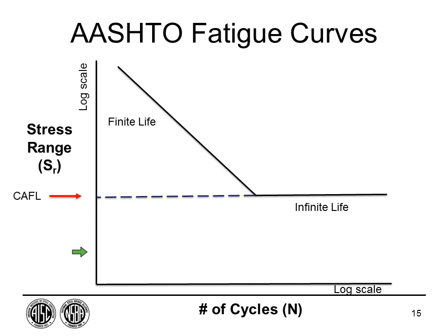And what that effectively says is, say the compression stress is -10, the fatigue limit state load cannot exceed a stress range of +10, or say, 9. It has to always be more. In other words, it can never go into tension even with the fatigue limit state truck. There is a provision in there to allow you to do that. Now, it could still crack.